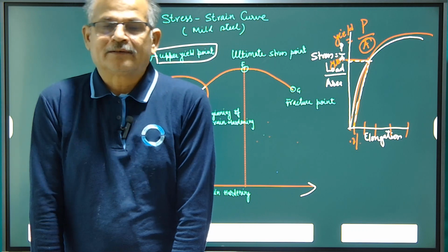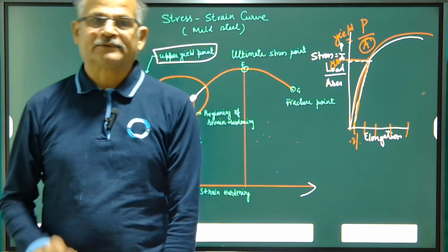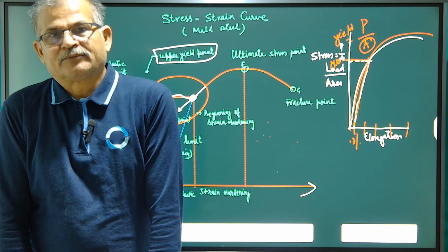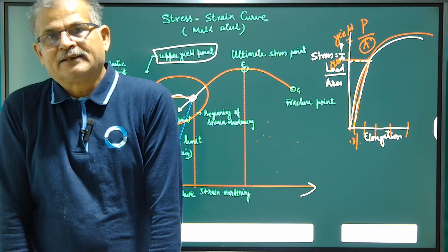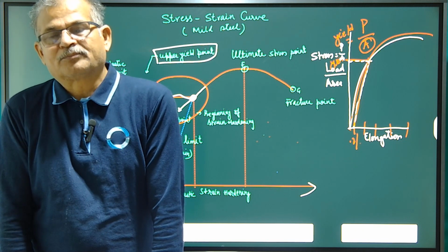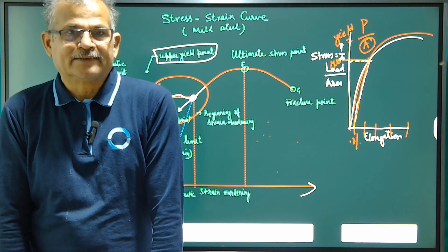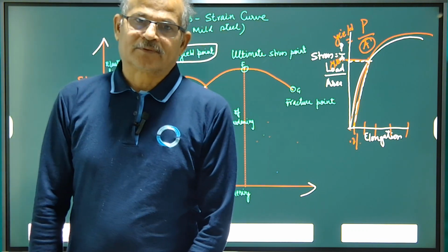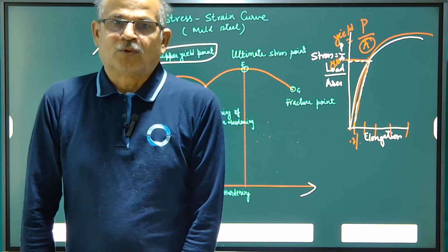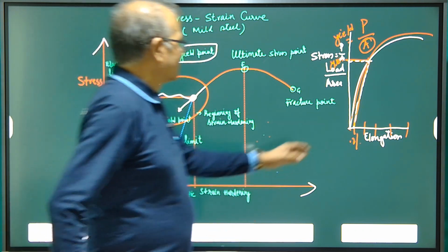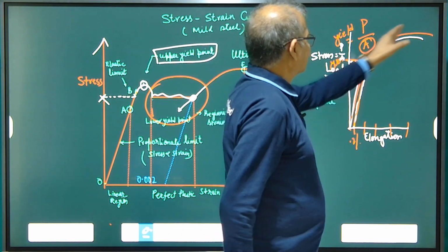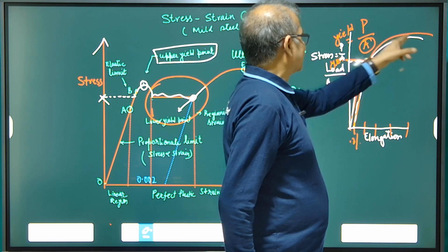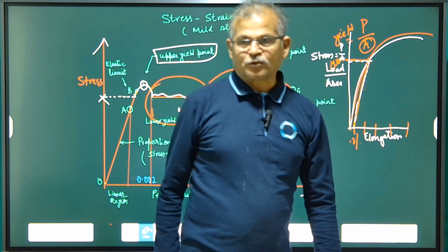That is the point, that junction is the yield point. So we know that in the mild steel case, yield point occurs, which is about 0.2% of the gauge length. So we determine the gauge length, which is 5.65 root A. Take the 0.2% of it, draw a parallel graph to the stress strain curve, and find out where it intersects the stress strain curve, and the corresponding stress is the proof stress.